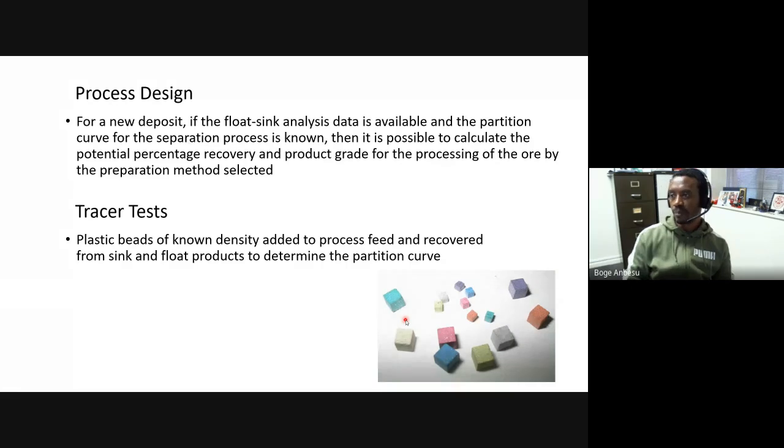So for example, you're looking at the new deposit, you have done your sink and float test, you have constructed your separation density curve or partition curve. Then based on that, you can make some nice conclusions. So if I target this much percent or that much percent, what is the expected recovery and grade and so on. Those can be predicted and inputted into your design as well. And there are some applications that you can consider from a typical